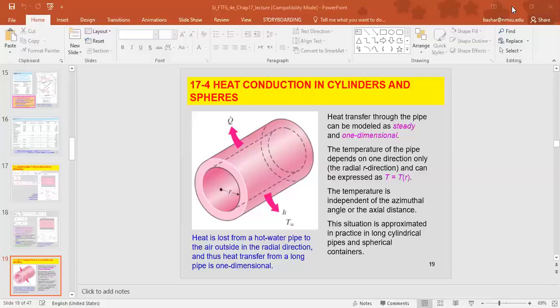Now rearrange the equation and integrate. We will have this form of the temperature distribution. What is the parameter b here called? b is h A_s divided by rho V Cp, and it's the reciprocal of the time constant. So this is not actually the time constant, it's the inverse of the time constant. So the time constant equals 1 over b.